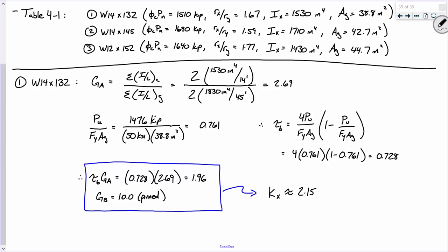Make sure that you're lining up with the right marks, okay? For instance, if you're on the 2 side, the distance between each one of those marks is 0.2 between 2 and 3, okay? So like 2, then tick, tick, tick, tick, 3. So that's 2.2, 2.4, 2.6, 2.8.